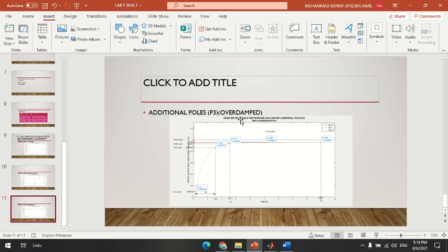So we found that the poles of the input generate the forced response, whereas the system poles generate the transient response. And if the system poles are real, the system exhibits overdamped behavior. Those exponential responses have time constants equal to the reciprocal of the pole location.